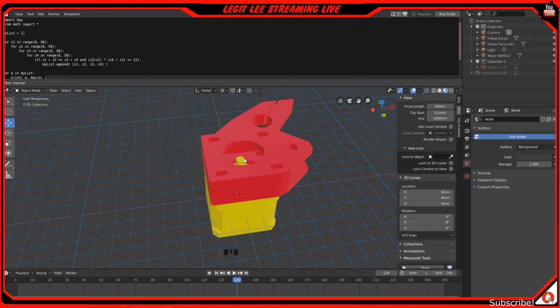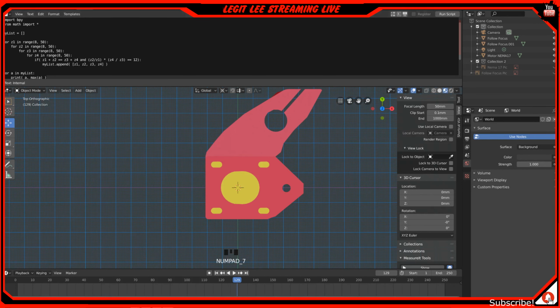And I want to have the gear ratio double that. So it will spin 2 times to get 1 rotation out of the second gear that's going to be spinning our camera control system, basically. So what I'll do is we'll do 15 teeth on the shaft gear and then 30 teeth on the big gear. So it's a 1-to-2 ratio because it's double the amount of teeth.